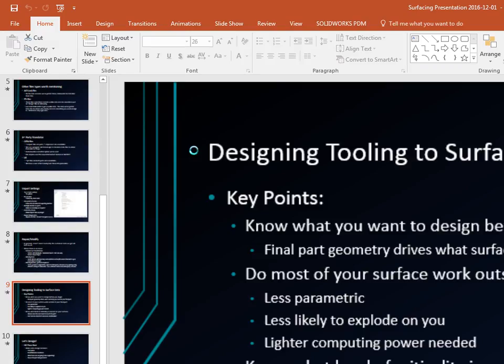into multiple parts. Now, you said that you would actually put the holes in there as well, a time saver, but would you have to edit the hole positions as well for each one so they're idiot proof? Well, it depends on how you put your holes in. If you're dimensioning them off the edges, they'll move with it. If you're dimensioning them off the origin, that would be a problem.